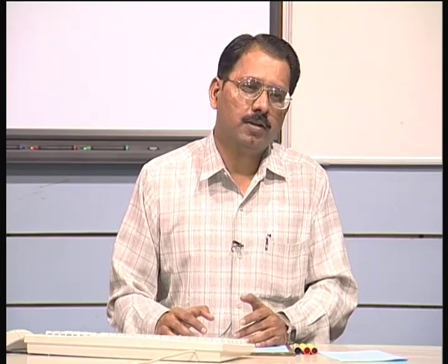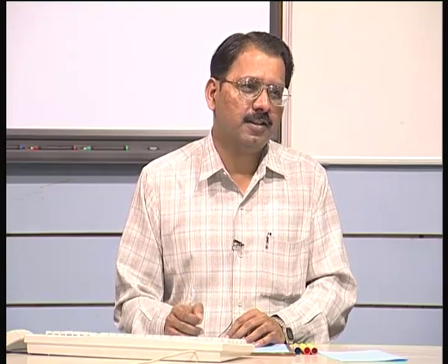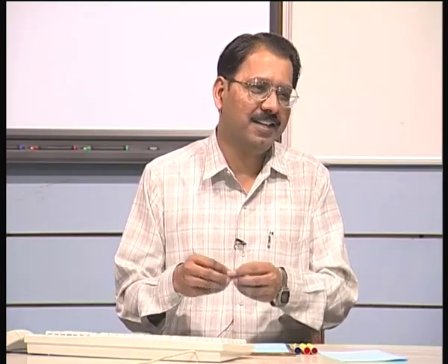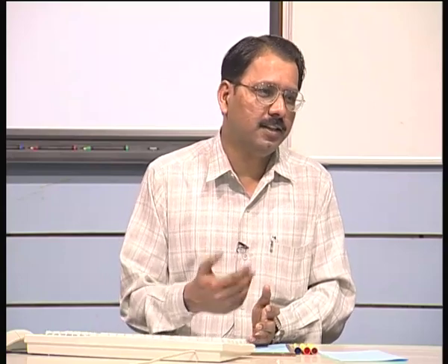Okay. Any other points? Voxel based modeling, voxel is filled partially? No, in voxel based modeling what you do is, suppose you just check the center of the voxel. If the center of the voxel is inside the object which you are trying to model, that voxel is considered to be completely full. So, this is an approximate representation. The resolution will tell you that. If the center of the voxel is outside the object, you say that it is empty.